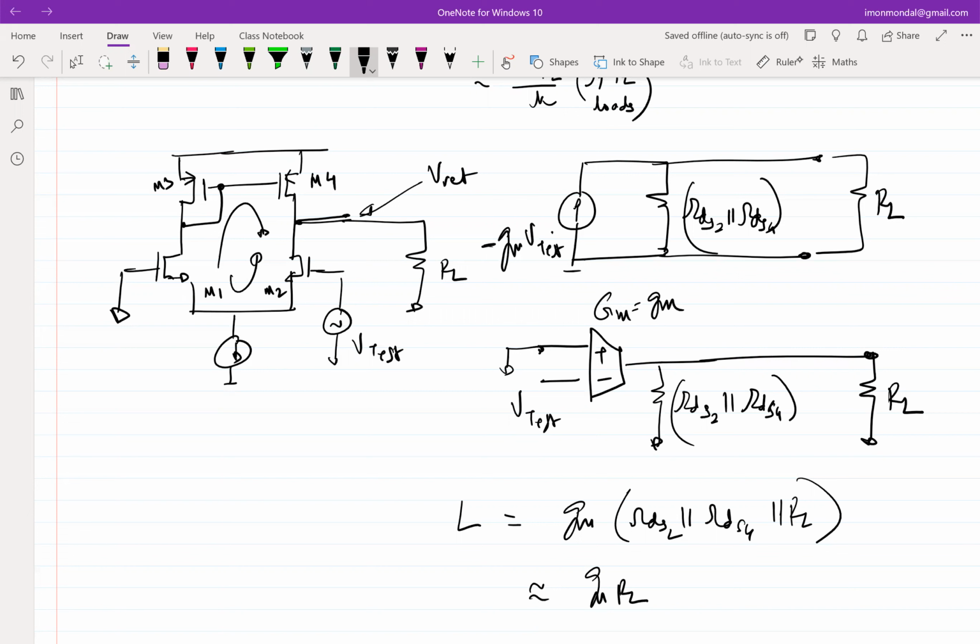For example, if you are using your music player, the load is kind of given. So typically those have 10 ohm, 20 ohm, 30 ohm loads, very small loads rather in that case. So you cannot really tamper with that. So what else can you do? Exactly, right? So you have to ensure that RL does not load the GM. So you have to put something in between. Yeah, right? So one possible solution is to use a voltage buffer in between the RL and the GM.